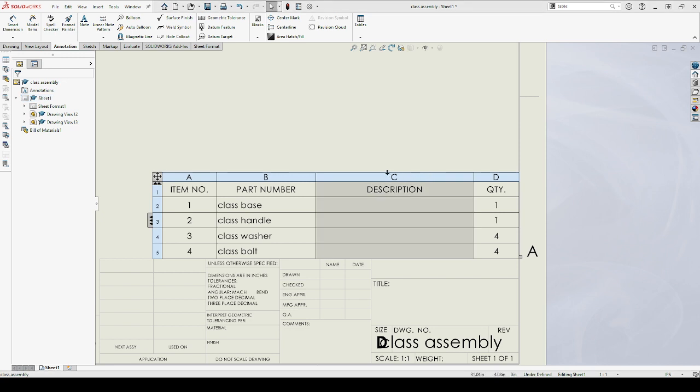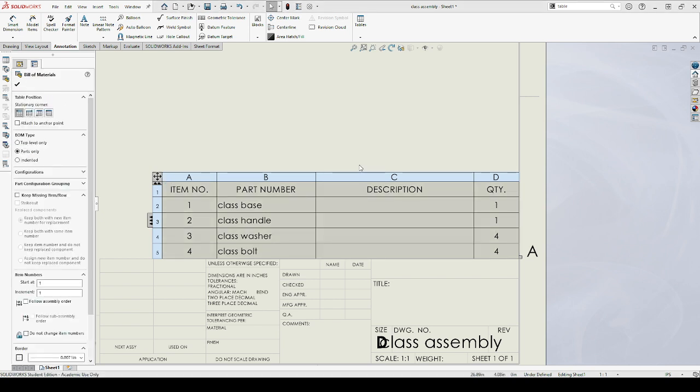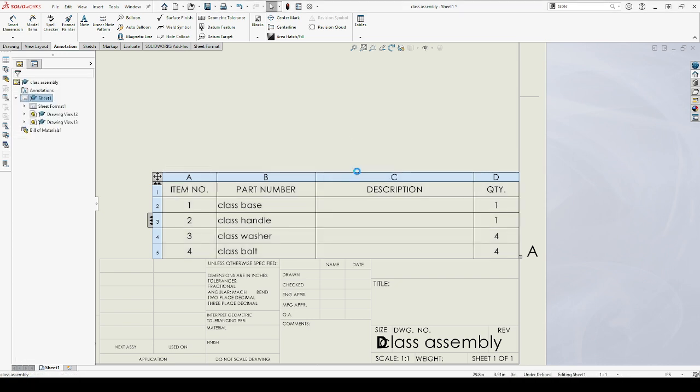And then you'll get this pop-up box here where you have to go here to where it says column property. The reason why I say make sure you do that is because if you come over here to where like the move button is or whatever, and I click there, column property is actually grayed out. So you want to make sure that you are inside that column or inside any column just so you can see that column property. And then you can actually add in a new column, set the material and all that stuff. I don't think if you hit for row, yeah, for row also, as you can see, it's grayed out. So you can't actually change or set or edit any column if you're not on the column area.